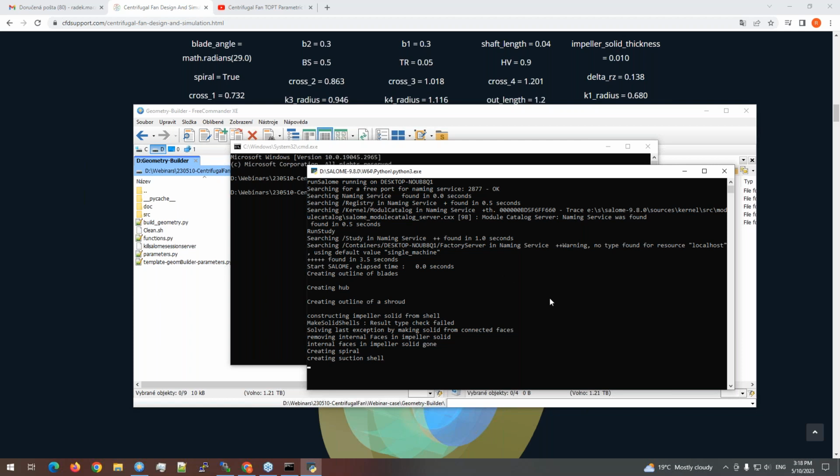The optimization can also be applied if you look for the best numerical parameters or the best mesh parameters. So you can vary any parameter which the TCFD workflow includes. For example, you can vary the refinement at a particular place or the overall refinement, or you can look for the best numerical scheme with respect to the optimization, or you can also look for the best relaxation factor to speed up the simulation and find a point where it becomes unstable, so you can optimize in this way. So yeah, the options are almost unlimited.